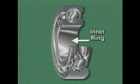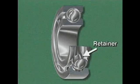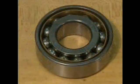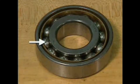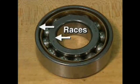While individual bearings may differ slightly, a typical rolling contact bearing consists of rolling elements, an inner ring, an outer ring, and a retainer. The rolling elements in a rolling contact bearing are either balls or rollers made of specially hardened steel. In this example, the rolling elements are balls, and they are set between two hardened steel rings, an inner ring and an outer ring. These rings are often called races.